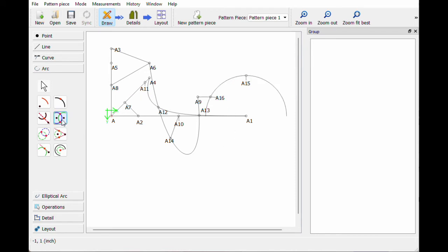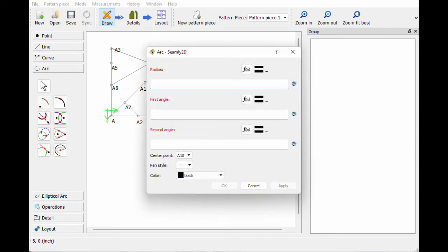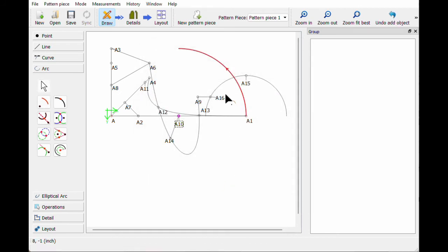This next one intersects 2 arcs. So real quick, let's make a second arc. Let's just start it at A10, radius of 5. Let's just say 0 to 90. Those should intersect. There we go. Yes, they do. Alright, so let's click this button, point of intersection between arcs. Go ahead and click that, and all we do is click these 2 curves, click, click, and it automatically puts a point where they cross each other.